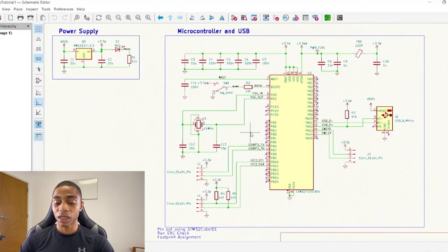All right, so we come here, we also have, as you can see, USB_D plus and USB_D minus, and these are differential pairs. And differential pairs are 2 signals with equal voltage but opposite polarity, right? So they're the same voltage level, but one is negative and one is positive. And this is done because any noise or interference that's common to both signals can be canceled out that way. And that just allows for better communication across longer signals or longer wires. So that's what differential pairs are.